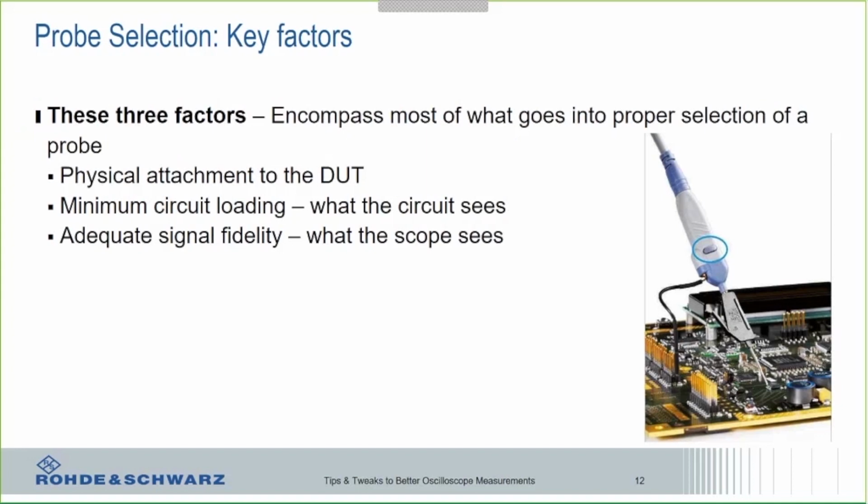And so that's the second piece. You really want to select probes that are going to have a minimum of impact on your device under test. When we talk about that, we'll often talk about the loading of the probes and how that can come through and affect what your actual circuit sees on the board.